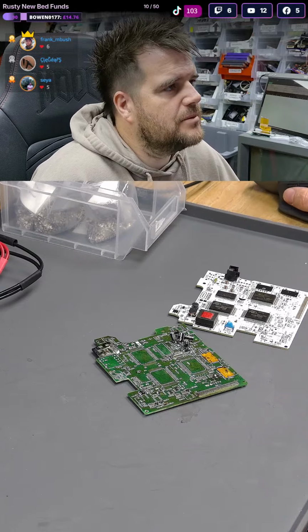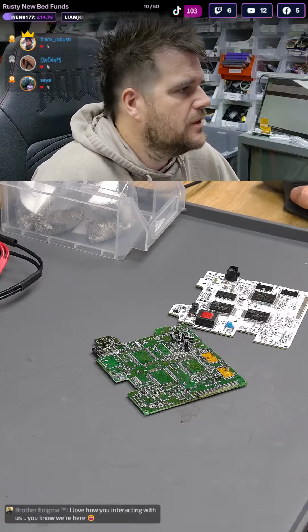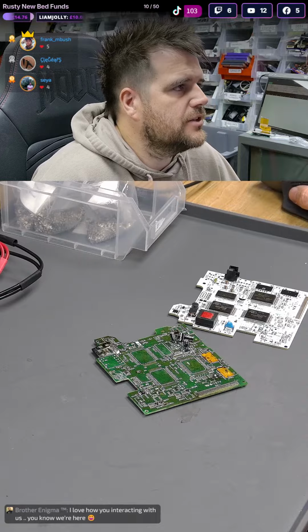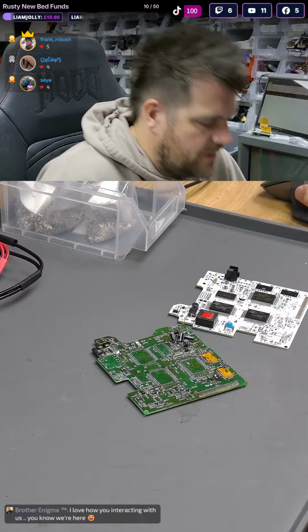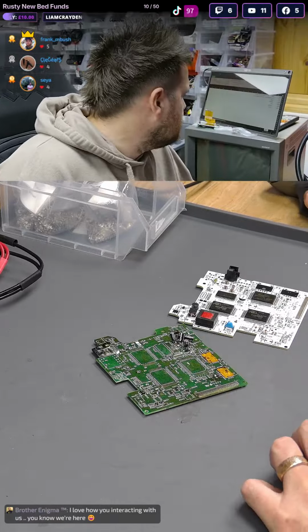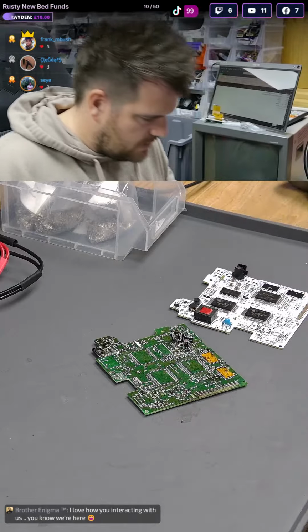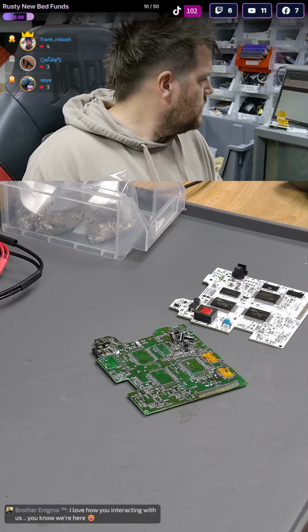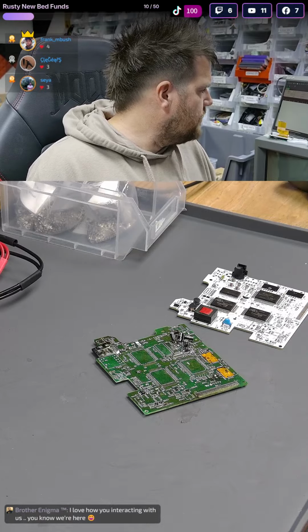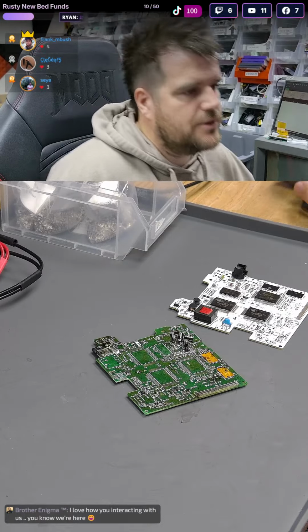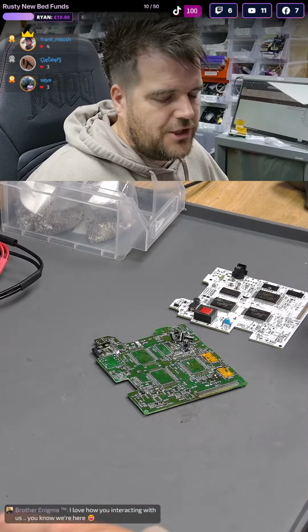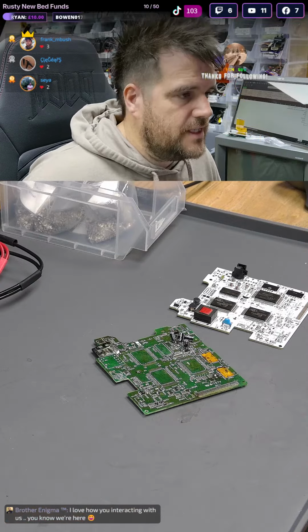I kind of want to see a bit more detail about where it's going, but I've got to trust the equipment, and that is literally what it's measuring. So let's make that note. It's C723, 1.5 nanofarad. And these are the kind of caps that if you're using a cheaper LCR meter, you'd never get this accurate reading, and you'd be way off.